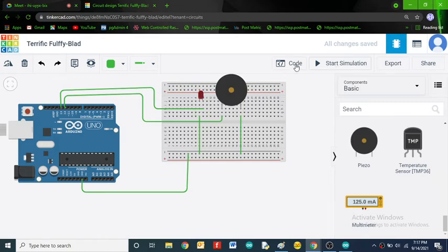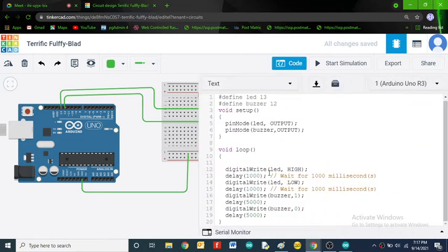But here this is the delay method. First it will turn on the LED because of the sequential execution order. It will wait for 1 second. So delay is nothing but what? Your processor is in the idle mode. It will not do anything, it just remains in an empty loop. It will count for thousands of counts, and then it will wait for 1 second.